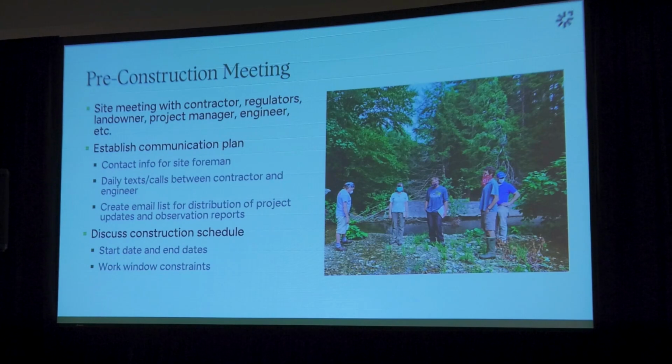So a pre-construction meeting is often required by permits. This came up in the last session. It's really on site to go through permit conditions, what's going on, what the schedule is, what the sequence is, and to identify all the project team's roles and who's doing what. One of the things I really stress at the pre-construction meeting is that communication is key to a really good project, and understanding who's communicating with whom about what and when is really important here. It's also the time to establish anything the contractor feels they might be doing a little differently from the plans, to make sure that's approved right up front.